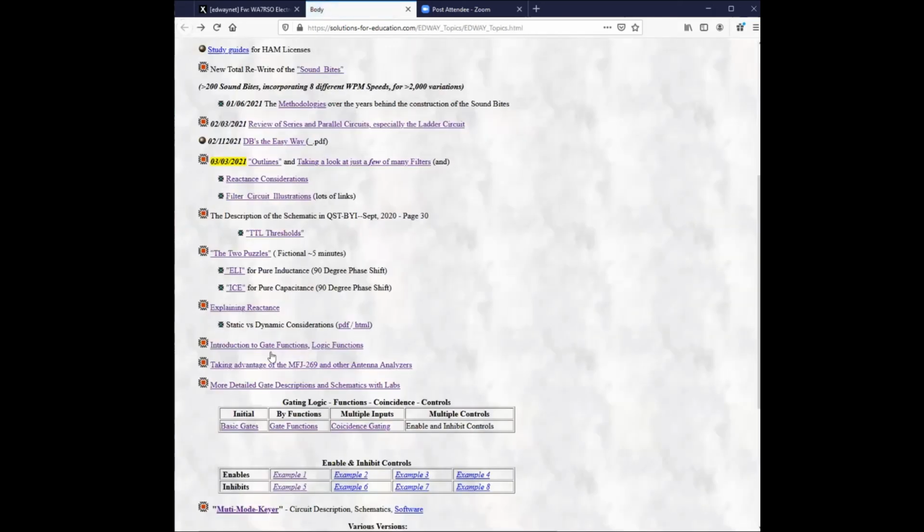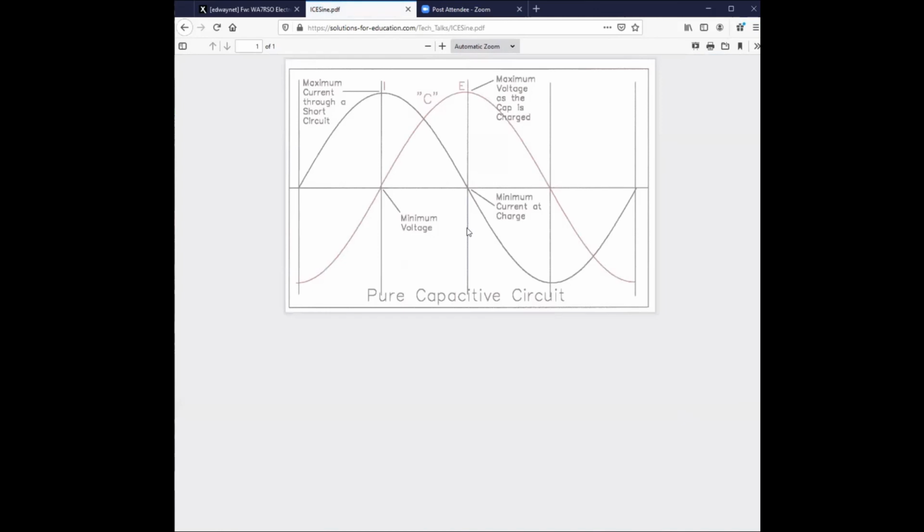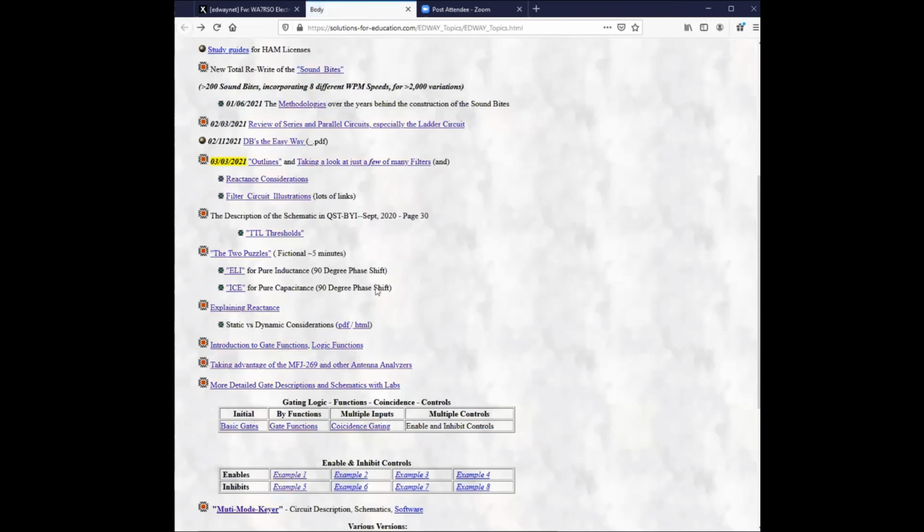In that same respect, if you go to the other one, which is ELI the ICE man, here in a capacitor, current leads the voltage. This is exactly what I was talking about on that power supply. Since you have a 90-degree lag here, and a 90-degree lead of the opposite value with coils, you can see that between the two you can have a 180-degree phase difference. Then from there, we can get into things like power factor and such.